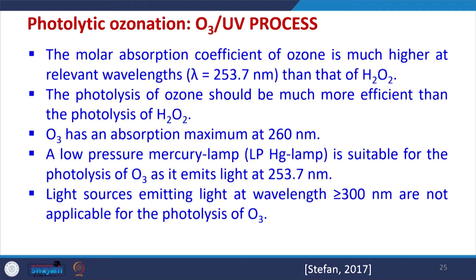The molar absorption coefficient of ozone is much higher in the relevant UV wavelength range, like at lambda of 253.7 nanometers, which is one of the key wavelengths for destruction of pathogens. Under that condition the molar absorption coefficient of ozone is very high as compared to that of H2O2 itself. So, the photolysis of ozone is much more efficient than photolysis of H2O2 itself.